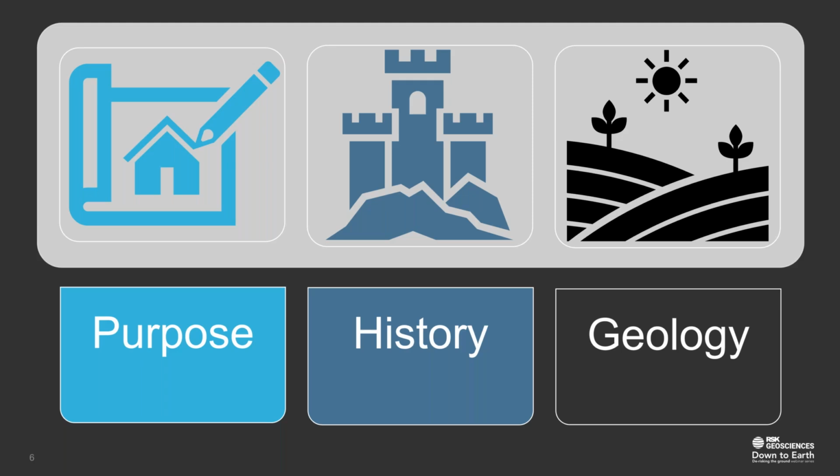What is the history of the site? Important things you need to think about might include, were there any quarries or ponds or backfilled material? Is there any old buildings on the site or footings, or perhaps there's been some footings demolished that are still underneath? Any basements or marshland? Is there any current or historic cuttings or embankments on the site or adjacent to the site, as things just off the sides to your site could affect you too? Are there any steep changes in topography or slopes, again, on-site and off-site?